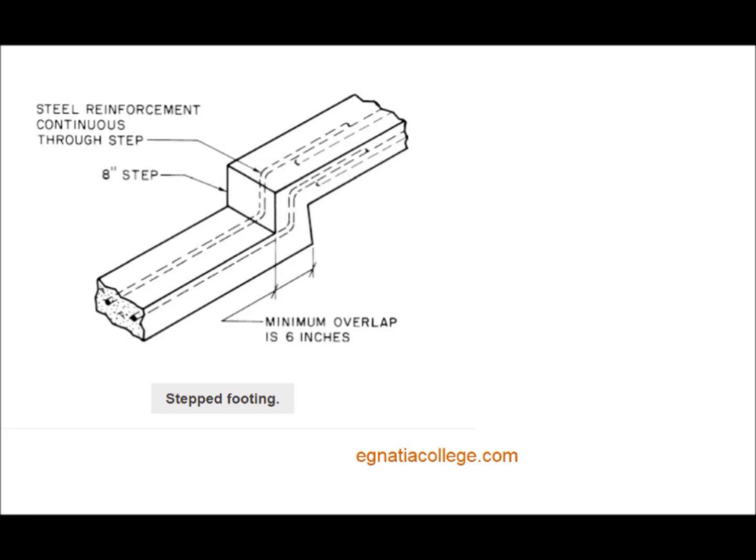For example, see the east side of the garage. This is shown on the east elevation 2 to 3rd. This step is also shown on the foundation plan. It is 8 feet 0 inch from the north end of the garage. Normally the two levels of the footing should overlap each other. The stepped footing shown on the east elevation does not appear to overlap.